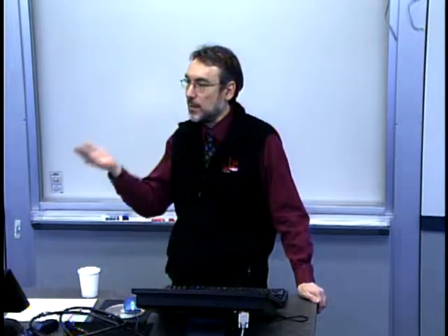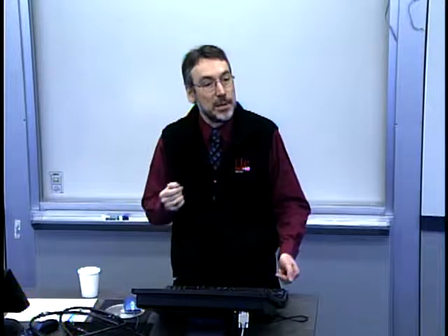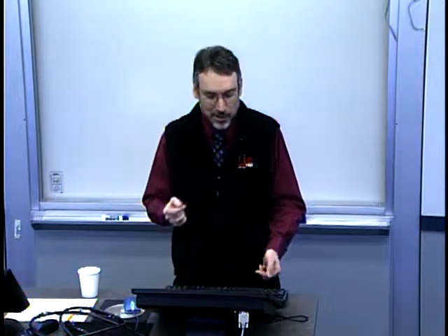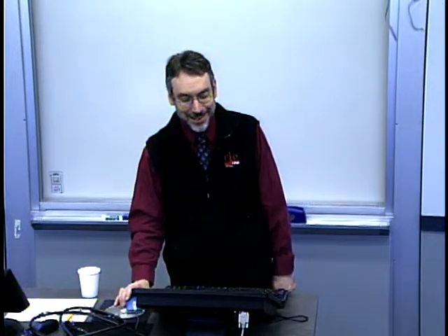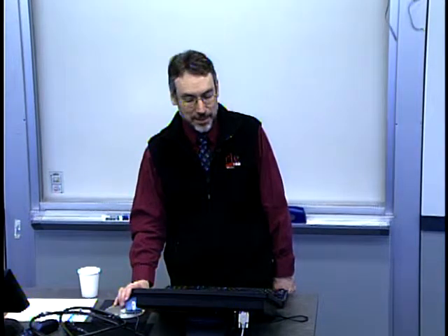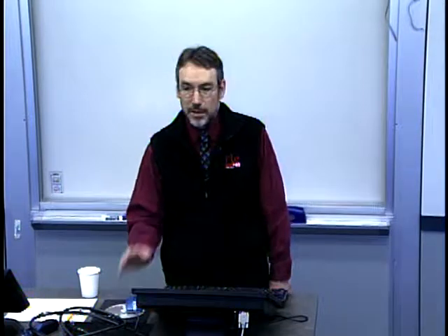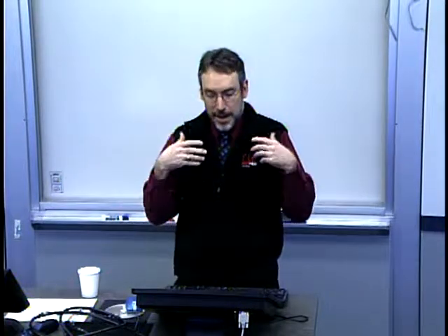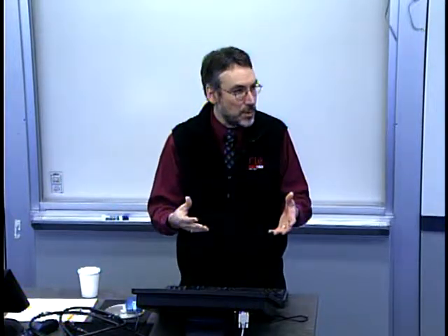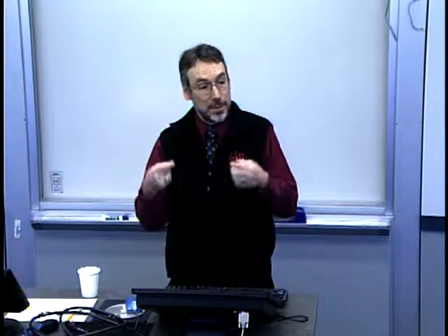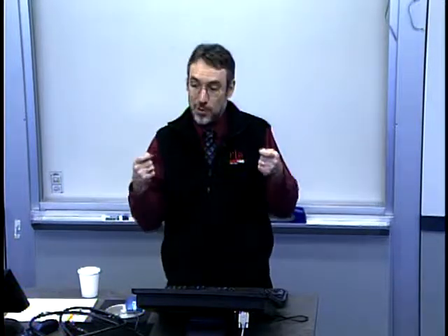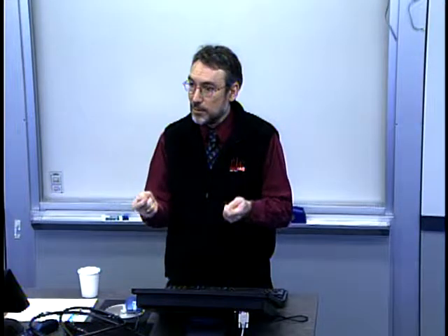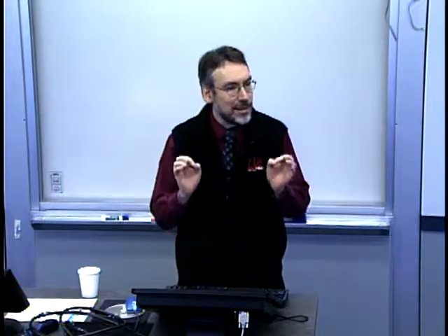So one might even apply some statistical methods to ask, is there a statistically significant mean difference between this set and this set of data? So it may look like a long-term trend, or it may simply be a reflection that there is a setup change on the equipment when a new shift comes in, or there may be just inherent differences in how the operator interacts with the equipment, right? How they load the part might be slightly different.